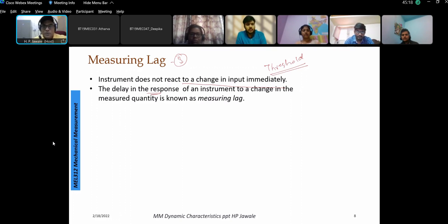The same thing is going to happen because of the different components in the measurement system, say primary sensing element, VCE, VME, and so on, either the functional or the real instrument, the physical elements in the instrument. The primary sensing element senses and gives a signal to the variable conversion element, which responds and gives some output, and it is transferred to the display. So the time between applying the input and getting some display at the instrument, for dynamic response, meaning change in the signals with respect to time, we call the measuring lag.